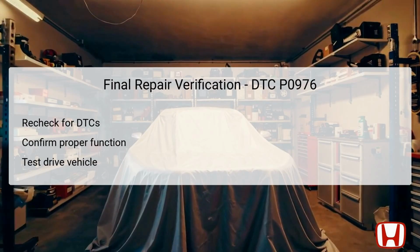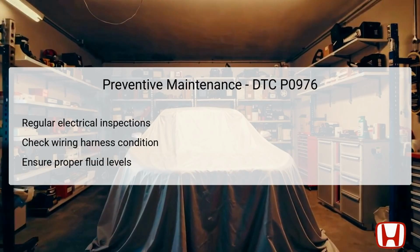If the transmission shifts smoothly and operates without triggering DTC P0976 again, it suggests successful repairs and restoration of the system's integrity. Preventive maintenance plays a vital role in avoiding future issues concerning the shift solenoid valve B and related electrical systems. Regular electrical inspections should be conducted to identify any visible wear and tear, including frayed wires, corroded connectors, or any signs of moisture intrusion in connectors that could lead to shorts.